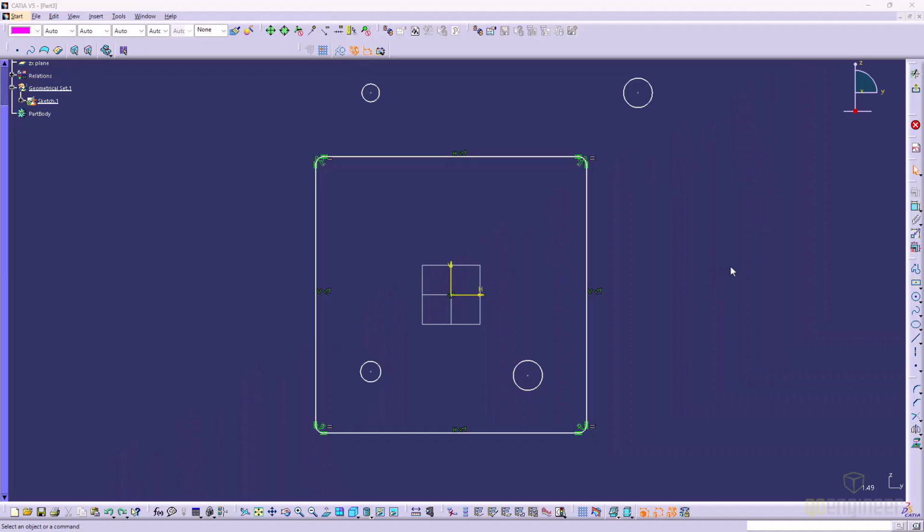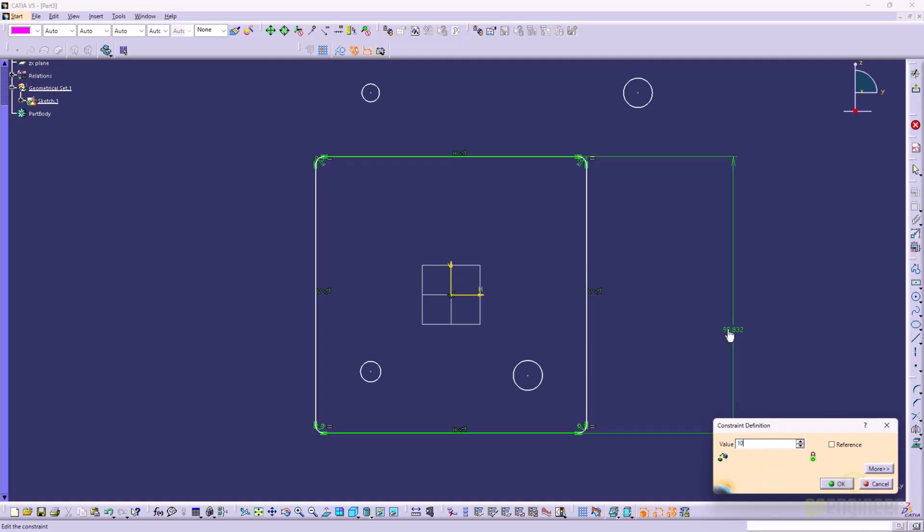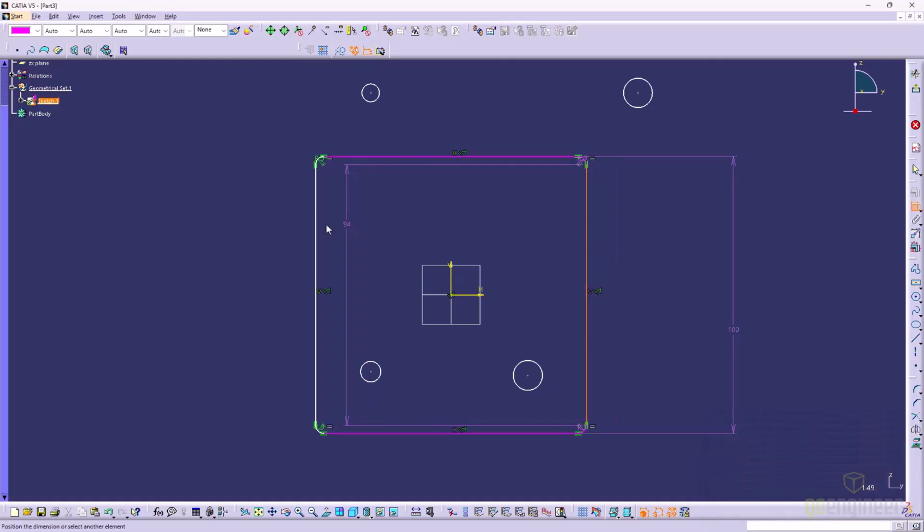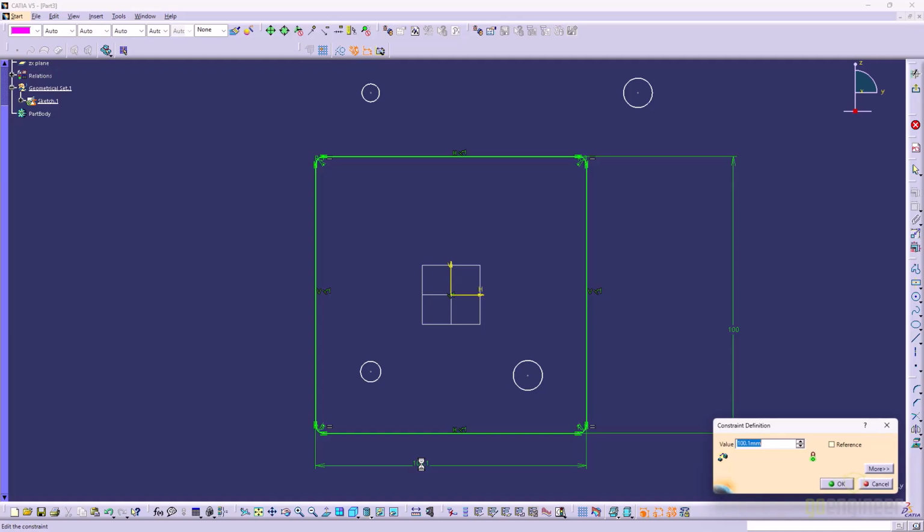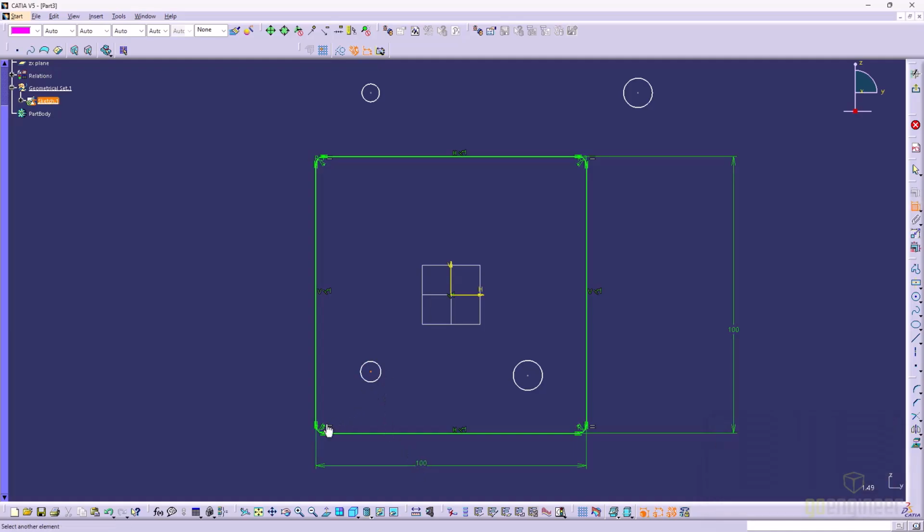Within the Sketcher workbench, to generate part constraints efficiently, utilize the contextual menu for sketch constraints. Double-click the constraint command to repeat it. When a geometric constraint needs to be applied, right-click, utilizing the contextual menu to apply the needed constraint. Then you can add all the constraints within one command and don't need to worry about clicking the constraints defined in the dialog box over and over.